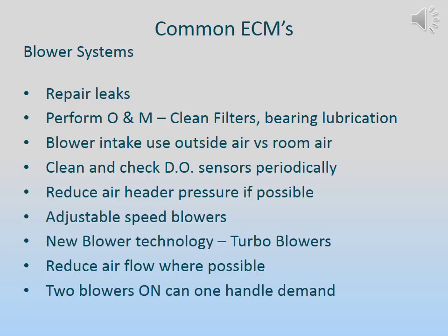Reduce the air header pressure by better control of the airflow rates and balance airflow rates to meet the needs of a specific zone. Use adjustable speed blowers. Consider a new technology that uses turbo blowers, which are more suitable for VFD control. Reduce airflow where possible and only use one blower if it can handle the demand.